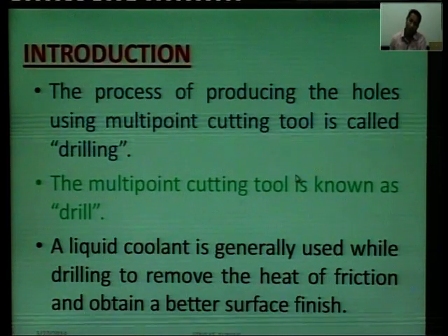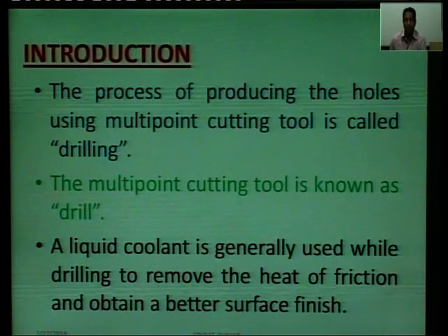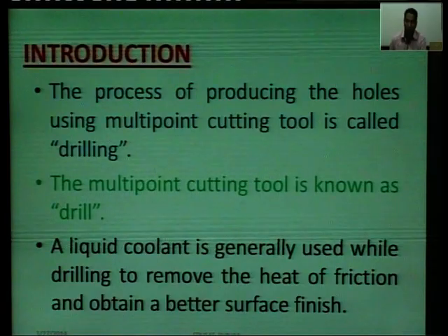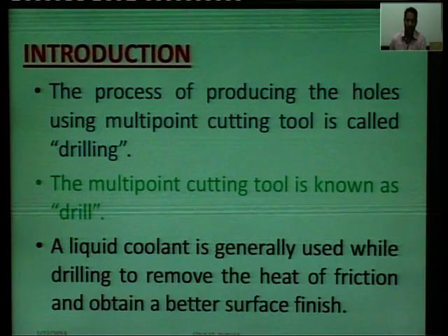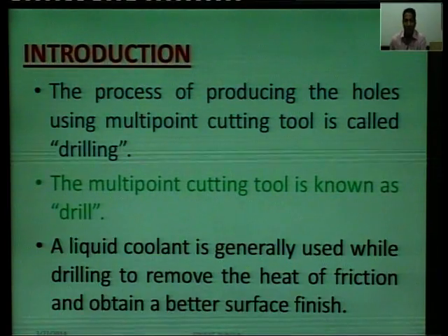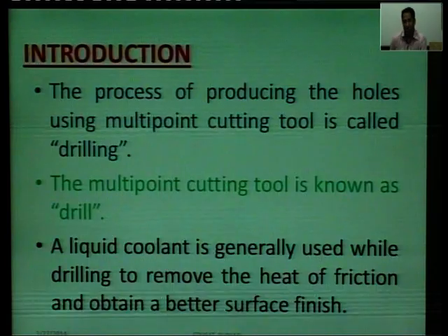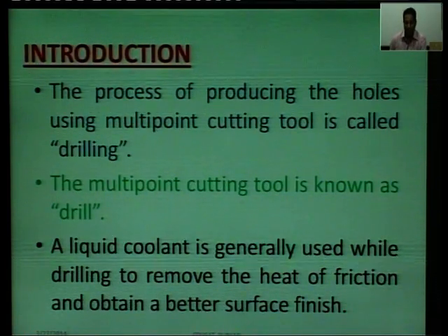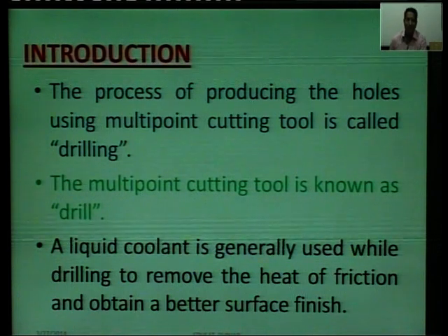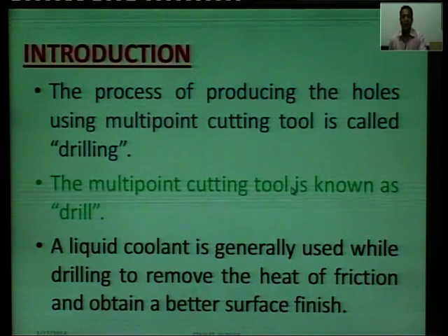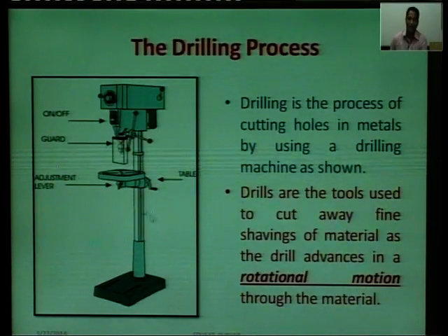Sometimes coolant is used. Coolant means, many times you have seen water is also used during the drilling operation to cool the tool as well as to remove the metal from the deep drilled hole. Sometimes coolant is used, sometimes it is not. The purpose is to take the heat away from the surface of the workpiece and to obtain a better surface finish. So this is the drilling process, my dear friend.